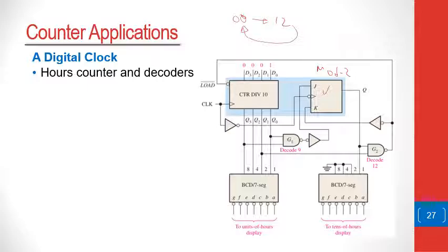And the way it will work is that when the count output here reaches 9, that is when we have 1 0 0 1, the output here will be activated, and this then will give you a 1 here. So you will get a 1 at the inputs. So whenever you record the 9, it will make sure that in the next clock pulse it activates this 1, so that the JK flip-flop is set so that you can have a 1 in the next count.